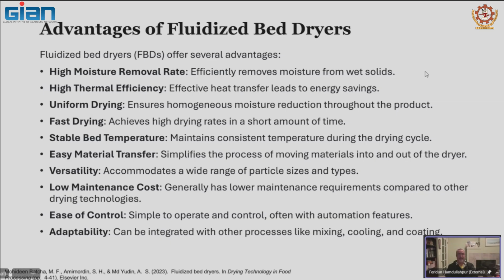So how much of that thermal energy are you transferring to the bed of solids in order to remove moisture? The efficiency of this thermal process is quite high. It's not great, because I'm also going to list it as one of the disadvantages that the hot air you're losing, unless you use it for another application.